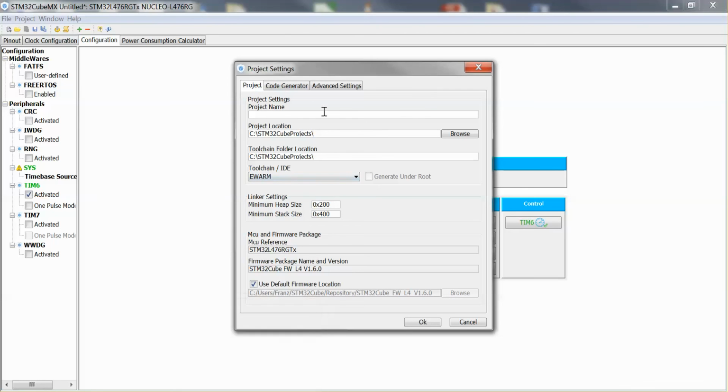system Workbench. Why so? Because basically what we want to do is we want to create the project in a folder. We want to create all the files needed and then import from that project. It doesn't mean that files will be copied by Eclipse into the workspace. They will be just linked. This is important because if you create the project directly in the workspace, you won't be able to import it because Eclipse will find a folder that already has the name of the project, and it says, I guess I already have a project with that name, so you won't be able to import it in your folder. So let's call it timer demo, for instance.